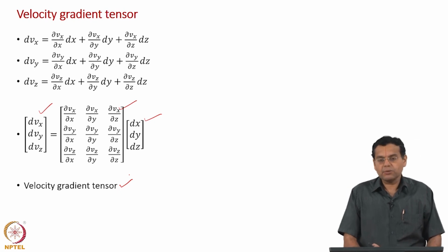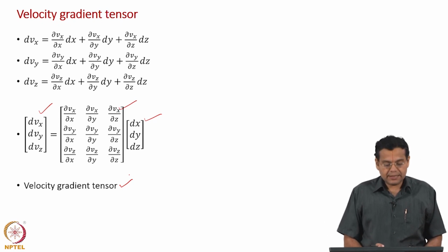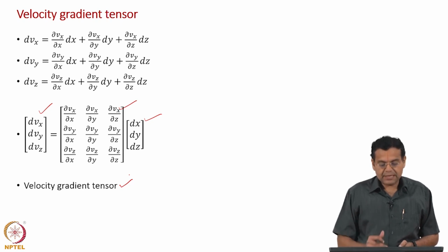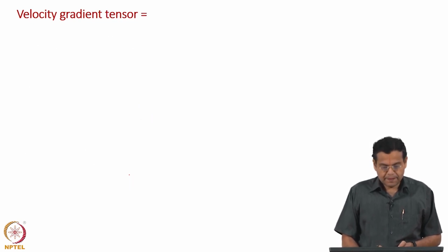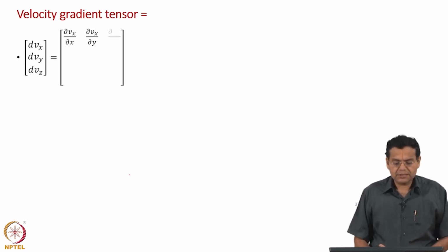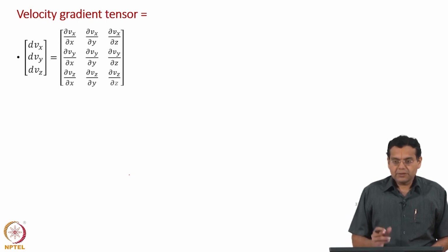Okay. So, what we have done now is derived an expression for the velocity gradient tensor by using the first method, which is the more mathematical method. Okay. We are not going to derive the expression using the second method, we will straight away write it analogously from our knowledge in solid mechanics. Okay. And that is what is shown here. So, this equation is from the previous slide, expressing velocity gradient tensor using the first method.